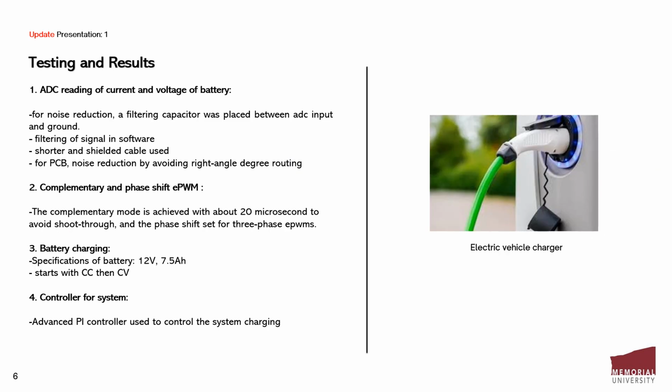Now I'm walking us through some of the procedures we took to build this reliable and efficient charger. Practically, we use the DSP board, and for the battery charging we need to take voltage readings and also current readings from the battery, which are used for PID control.